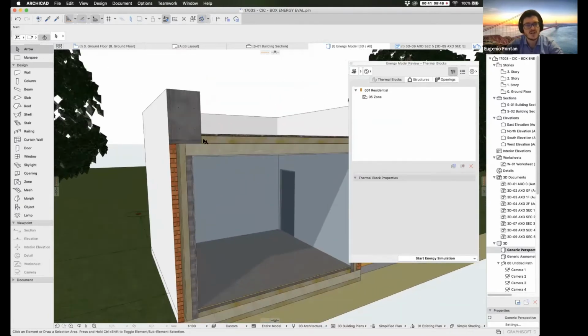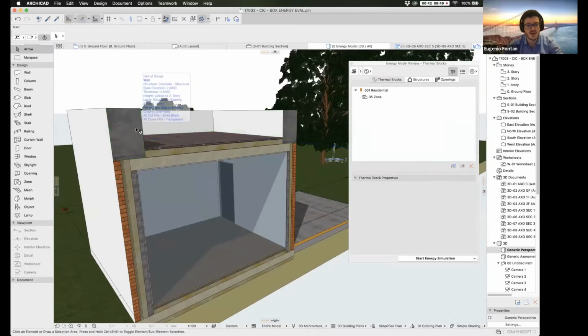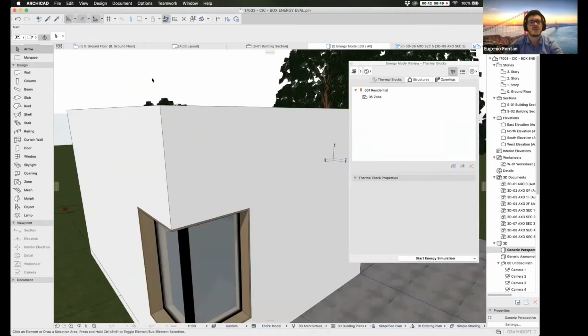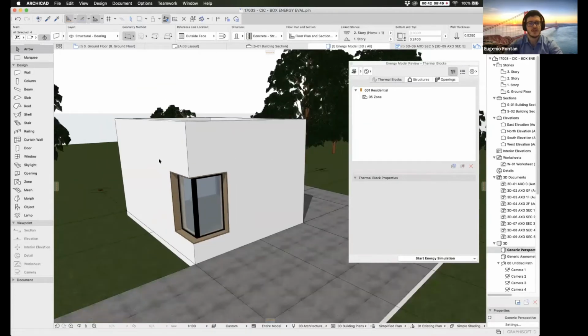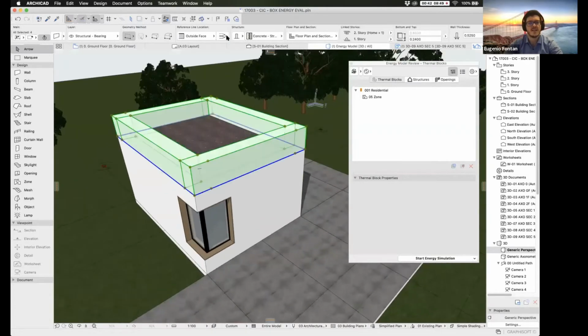And now we're going to change the parapet. This is a big chunk of concrete. So let's select the parapet on the outside. Okay, all the elements are selected. And let's now change the construction system to this. Instead of saying composite, there is one here. The third one is basic, composite, complex profile.